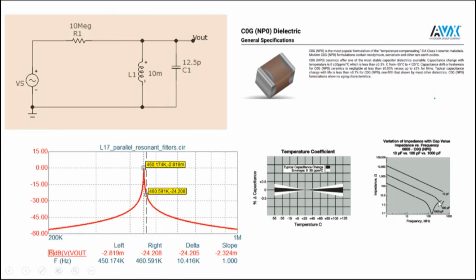So all capacitors have leads, and leads have inductance associated with them. They have some resistance associated with them. So note that at some higher frequencies, omega L, the little bit of inductance there in your capacitor leads, starts to become important, and you start getting distortion here. So all of your components, whether you pick up a resistor or a capacitor or an inductor, would fail at certain frequencies. They would not act like the inductance that you want or the capacitance that you want.